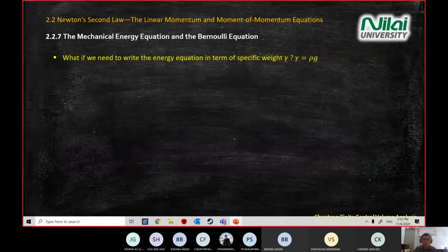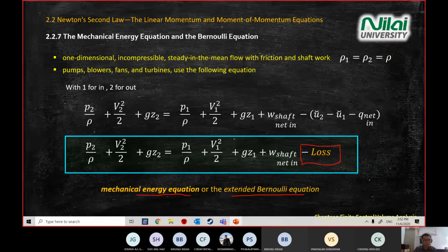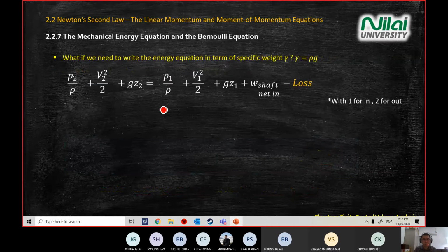Okay. Now we look at a few things with this question 46. Sometimes your boss or your client or your customer just provides you some spec, for example specific weight, or for the component itself, the component used to pump water. In the spec sheet you'll see shaft work head HS or head loss HL, total head, and all this. So you need to know how to calculate whether it is operable or not. Now, we have the equation that you see on the slide.